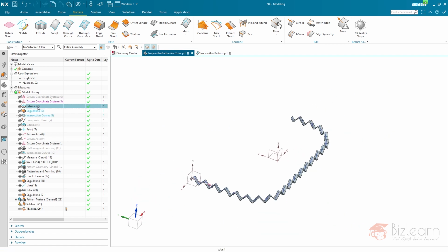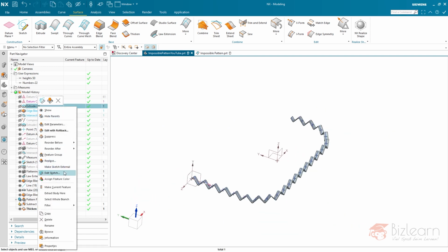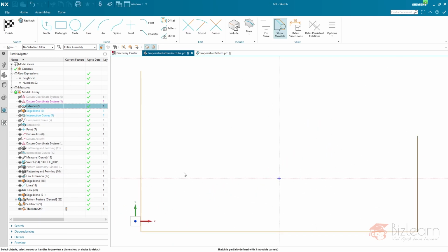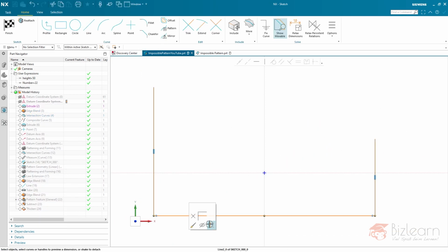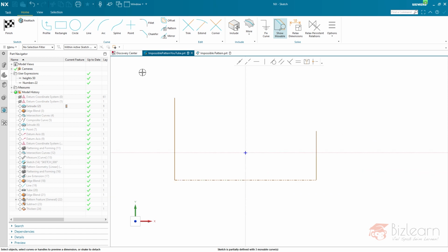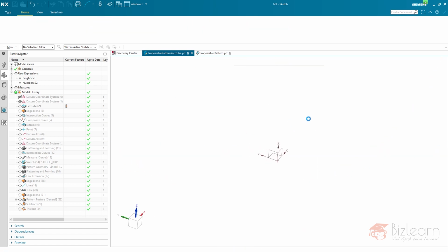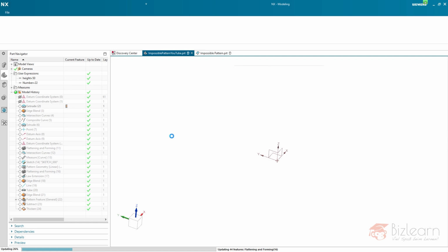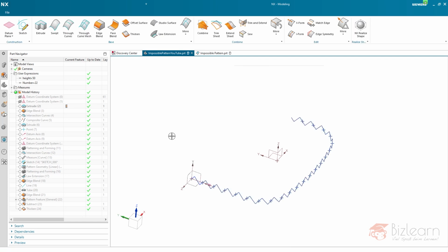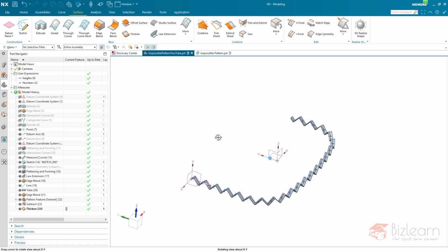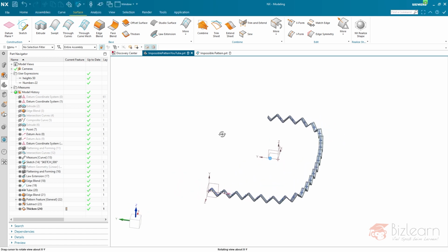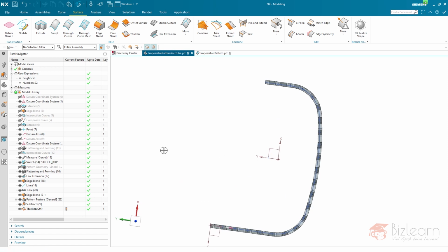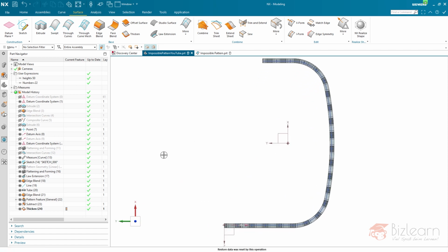The next thing you can try to do is, for example, edit the sketch from extrude number 2 in my case. Therefore, you can also create a dimension, which I'm not going to do right now. Sketches shall always be fully defined, but I'm just going to replace a line by a curve and see whether this is working properly. My expectation is that it does. Here we are. Also, this modification is working properly. Hopefully yours as well. Let me know if not.